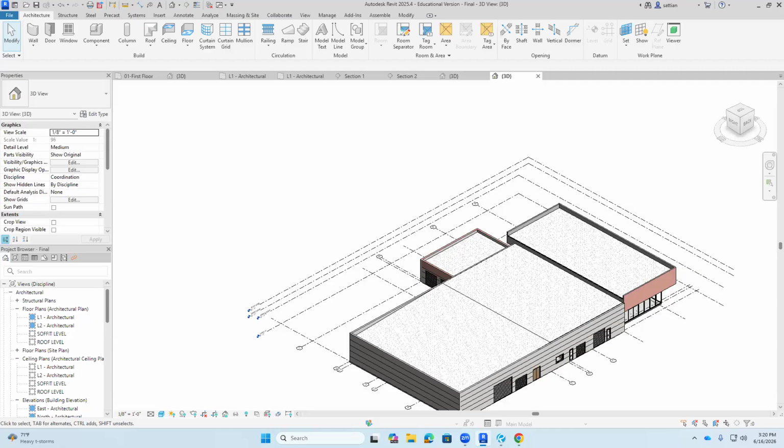You won't see it in door types. You can modify the top of the left arrow. Alright, now hover on the center. Hover where the door is supposed to be. Select the panel. Okay, you can use the drop down box where it says that. There's your door. That's also great.